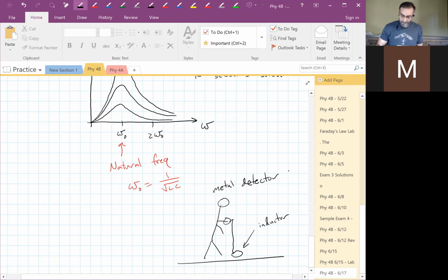It usually looks like a ring at the bottom. That's the inductor in the LRC circuit. It's a coil of wire. And what happens to the inductance when we put an iron core in the middle of it? When we talked about electromagnets, we put an iron core in the middle of the electromagnet, and it's much more effective. It intensifies the magnetic field in there.